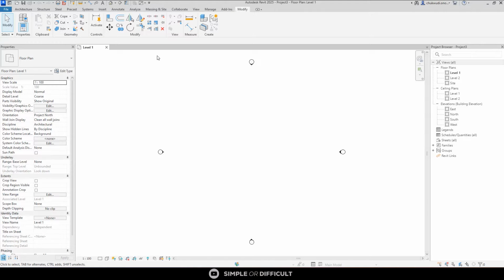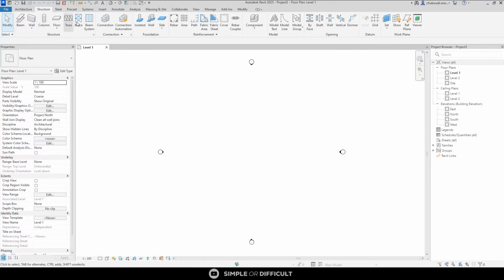Now, remember I told you that the Revit ribbon has 3 parts. The first part is these tabs on the ribbon. Use them to switch the ribbon that is displaying. The second one is the ribbon itself. Now, the third part, you look down here, you are going to see names. Those are called panels. This is what Revit uses to categorize these tools.